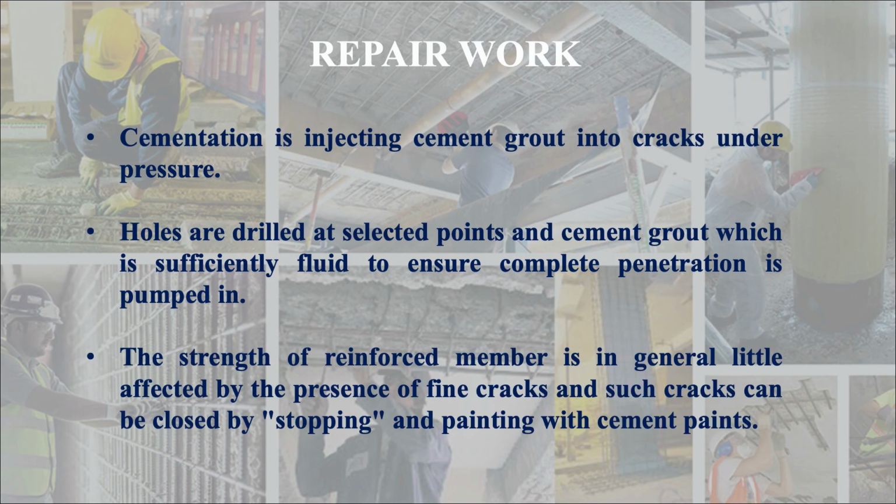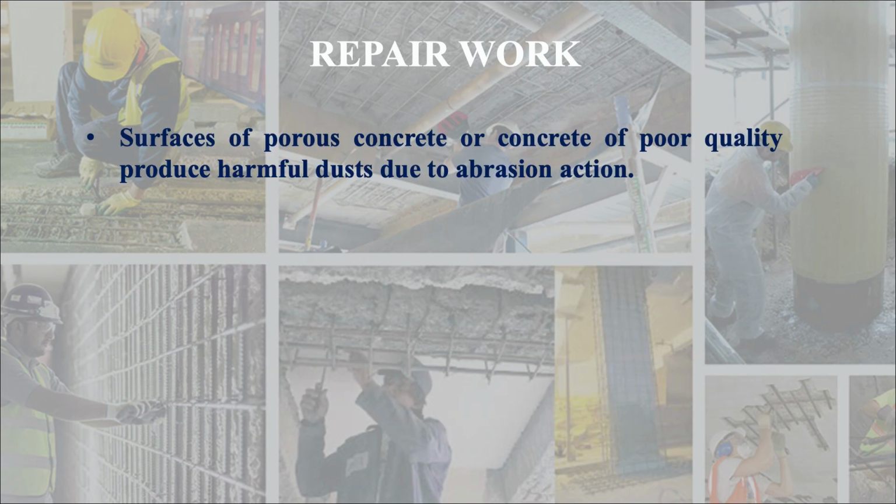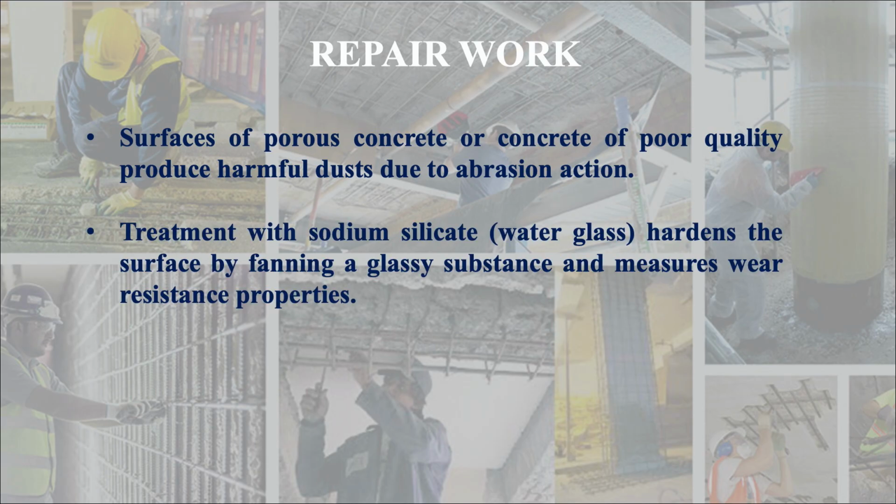The strength of a reinforced member is in general little affected by the presence of fine cracks. Such cracks can be closed by stopping and painting with cement paints. Surfaces of porous concrete or concrete of poor quality produce harmful dust due to abrasion action. Treatment with sodium silicate, that is water glass, hardens the surface by forming a glassy substance and improves wear resistance